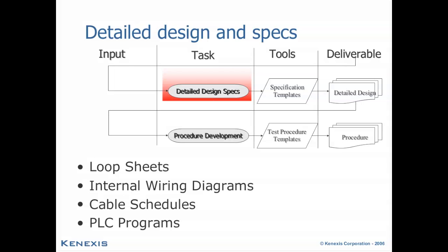At this point in time, things tend to look more similar. Even though this is a safety automation project, the tasks tend to look more similar to any other instrumentation and control project. The most important step at this point is to ensure that the implementation is done precisely as per the safety requirement specification, which, if done properly, should have codified all the requirements for the detailed designers in terms of how to meet those SIL targets that have been selected.